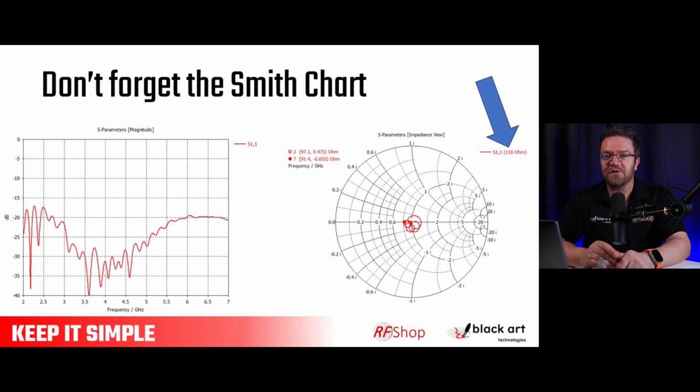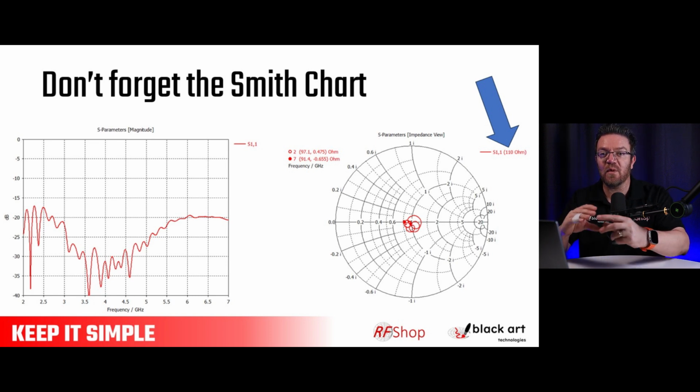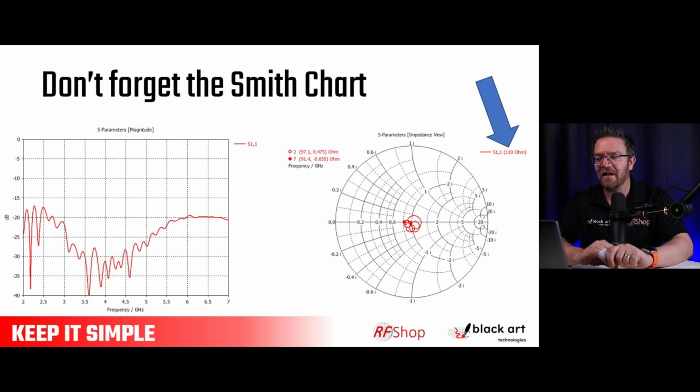Okay, so what you do in software, first of all, before you do more design work, you just change the relative impedance of your port that you're excited with. That's all you do, and there's ways then to translate that to something that you physically do as well. And the new value, which I can see there on the screen, is 110 ohm.